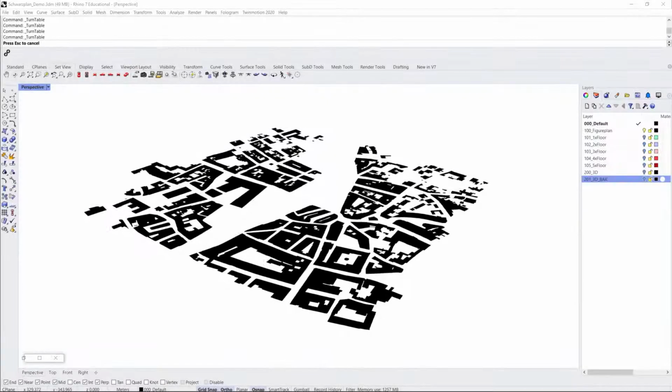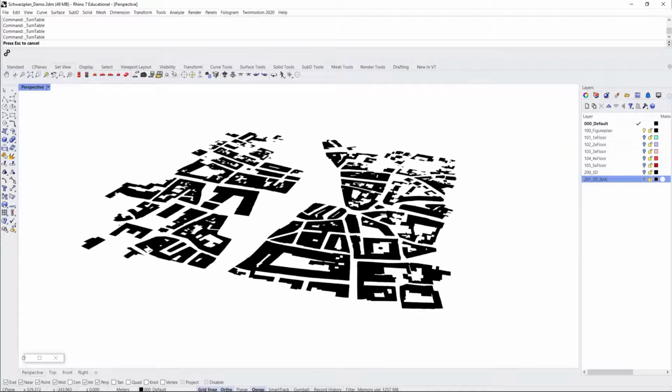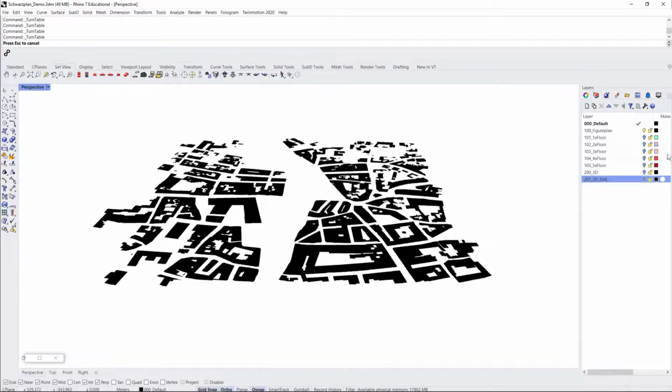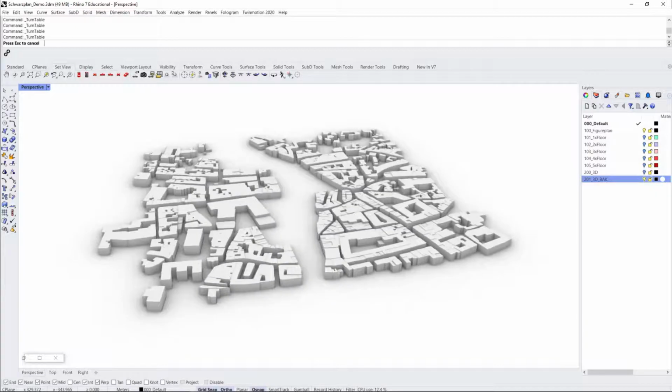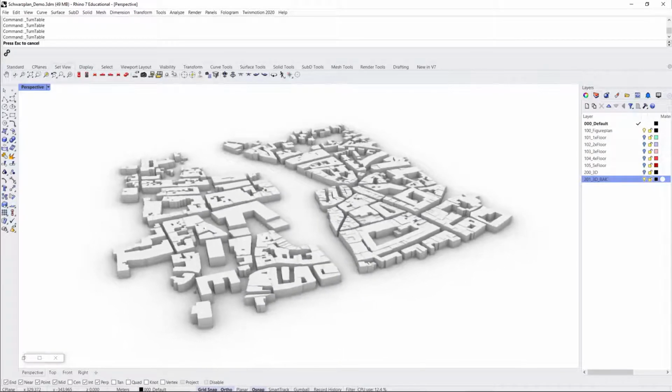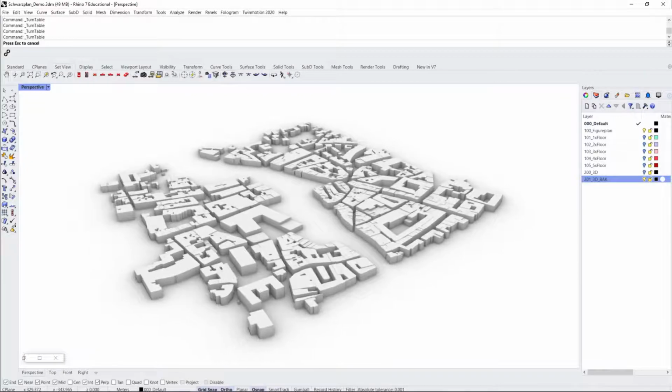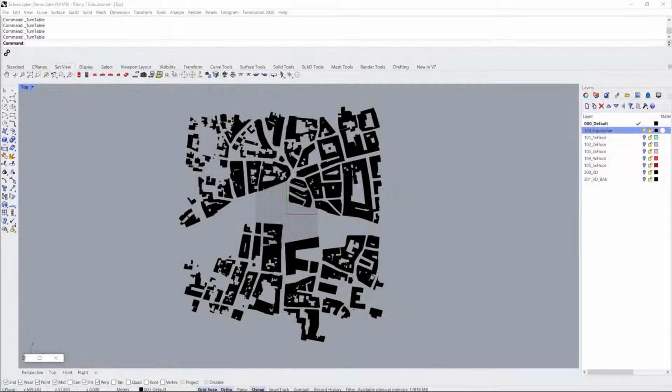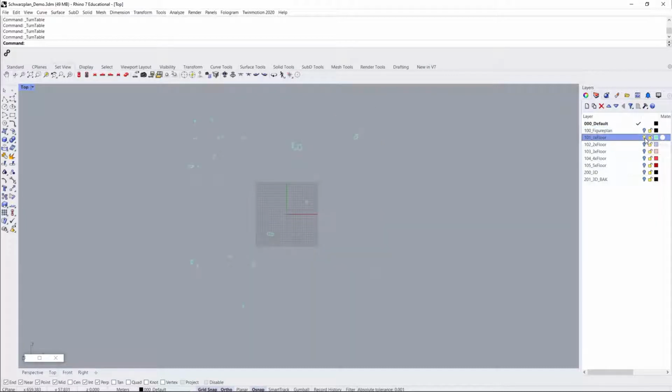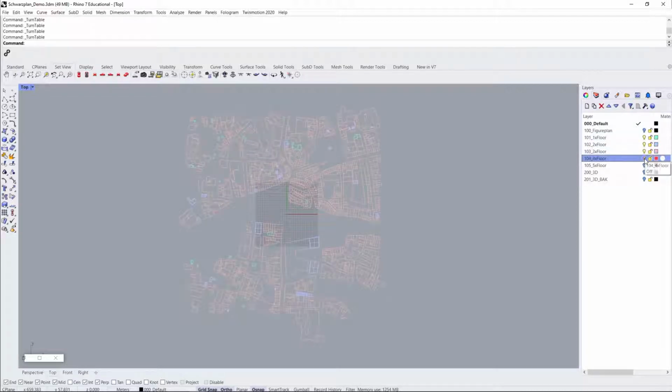I am going to demonstrate the advantages of using such an approach with the following example. We are going to basically cheat a believable 3D model from the figure plan of this city. The script I developed can be used on any figure plan if you divide the outlines of the buildings in layers according to the number of floors each building has. This information is readily available on any platform providing you with satellite or aerial views such as Google Earth.